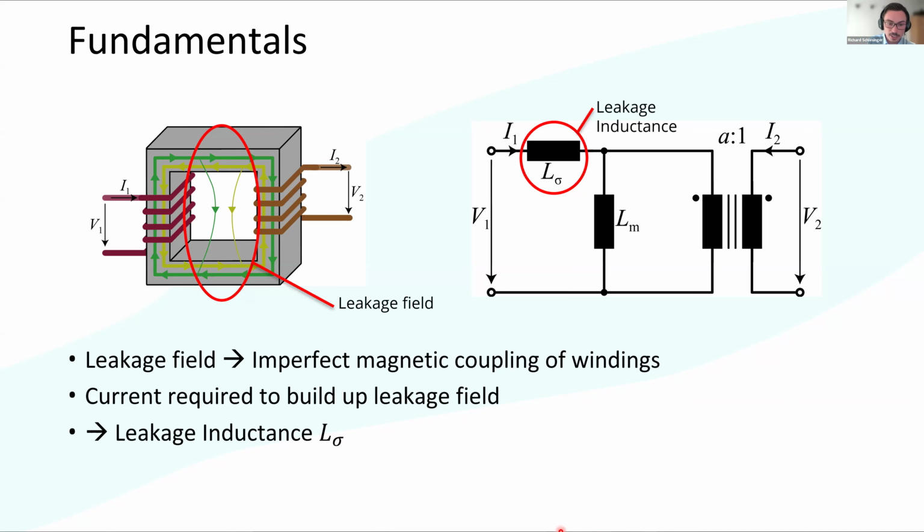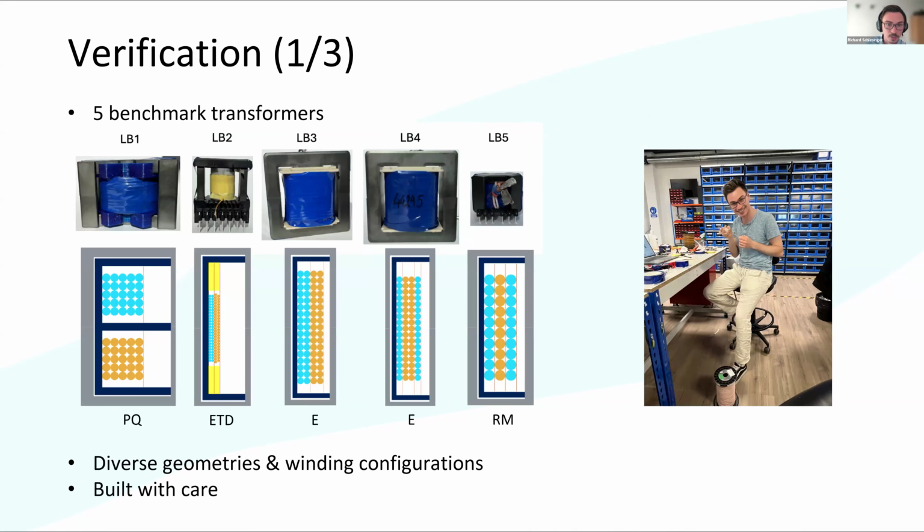So what you can do to minimize this is to twist the wires and make the loop as small as possible. This is especially problematic when you have a transformer like this, the fifth one, where we have a high transfer ratio. Because when we measure from the side with the higher number of turns and we have a loop at the other side, the inductance of that loop refracts to the primary side with the turns ratio squared. And in the case of this fifth transformer, that was quite significant.